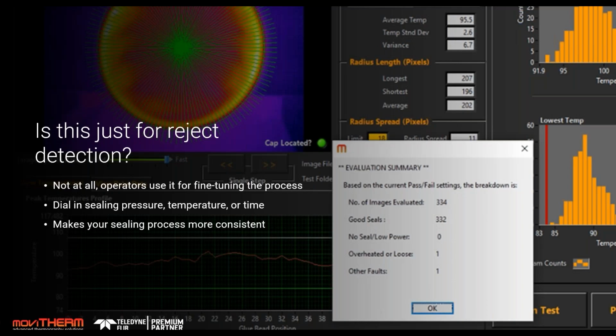You could change the torquer, and you're going to be able to immediately see what type of impact that has on the temperature data, right? So we're not looking at pattern recognition here. We're actually looking at quantifiable temperature data from the IR image. When you grab an image, we have temperature at every pixel, down to a 100th of a degree.